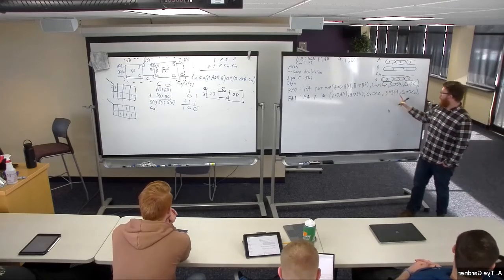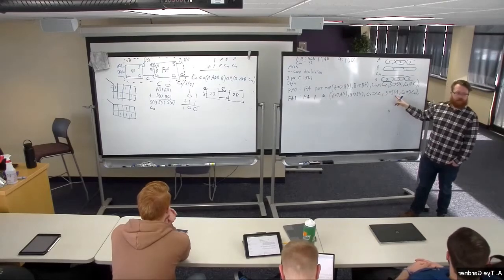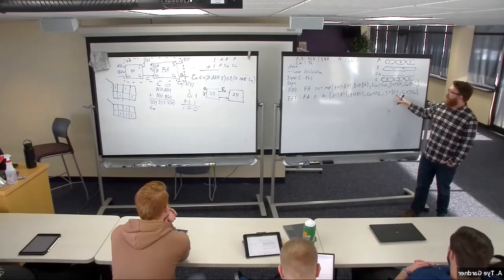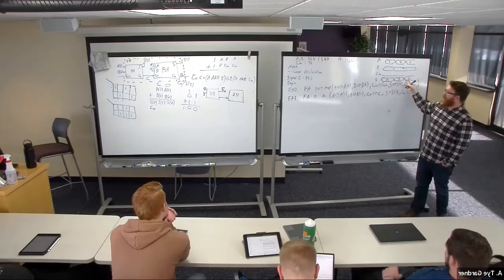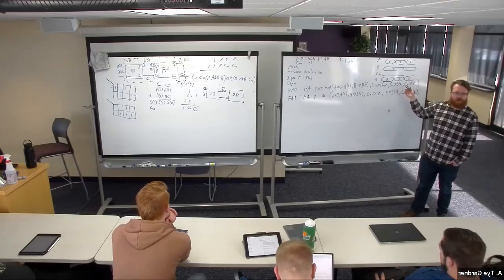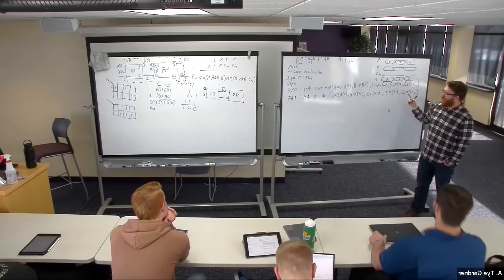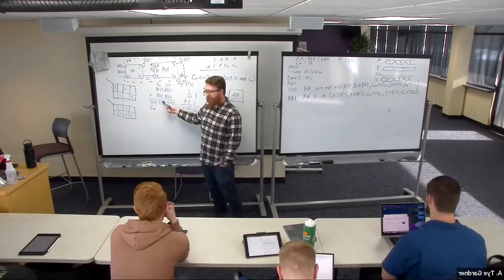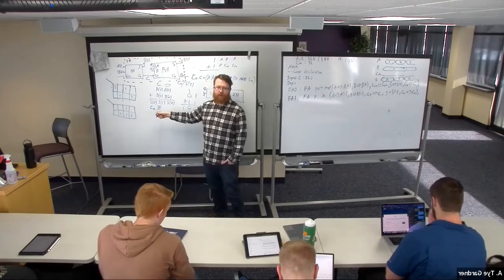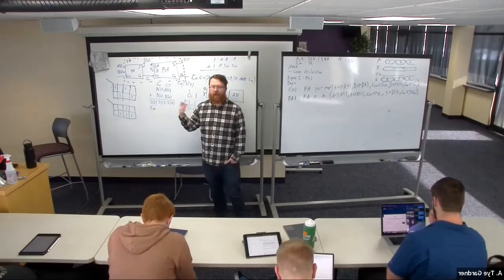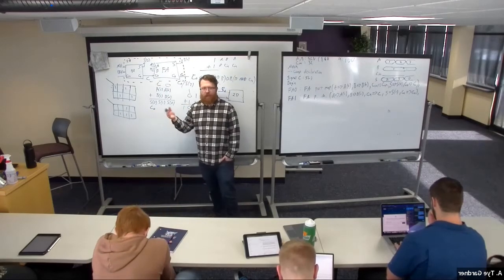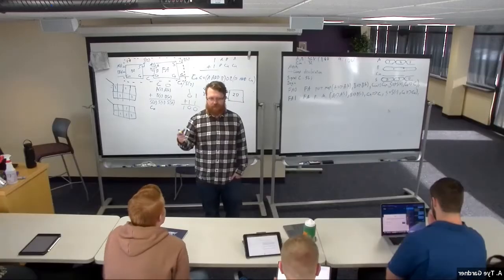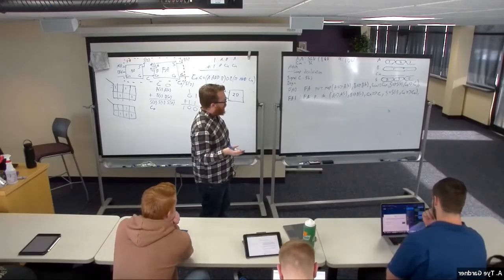Because sum is only 2 bits, right? It's 0 and 1. But what we will see is that the carry out value will be 1. So the sum is 0, 0, but the carry out bit becomes 1. And I have 1, 0, 0, the number is 4. I've written the test bench for you that will test that and make sure that it works.